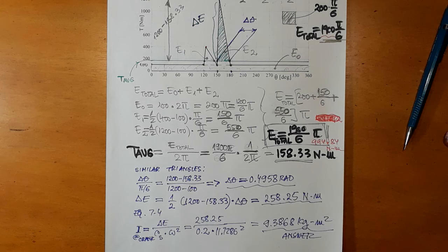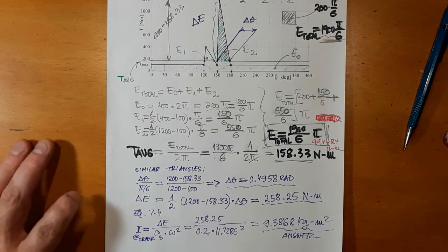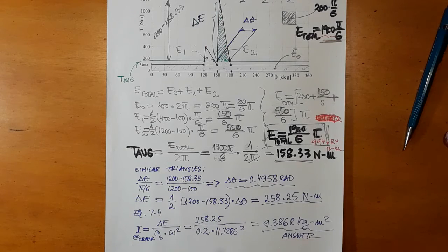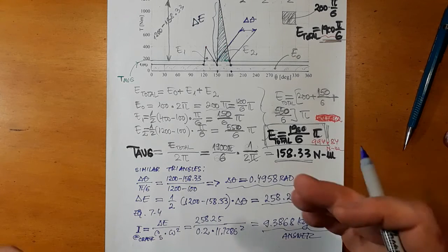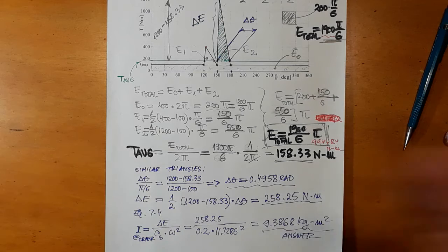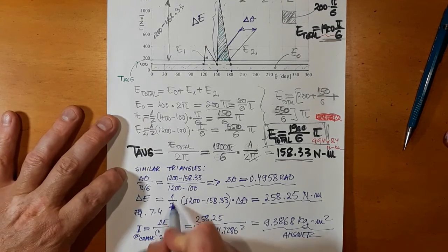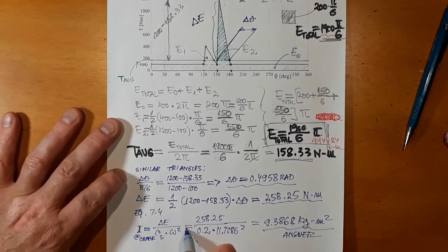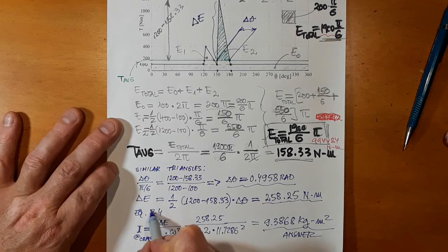Transmission ratio squared times smaller. But by placing it on the motor shaft, the transmission between the crank and the flywheel, could be gears there, belts, is going to experience all the overload, the pulses during the operation of the press.